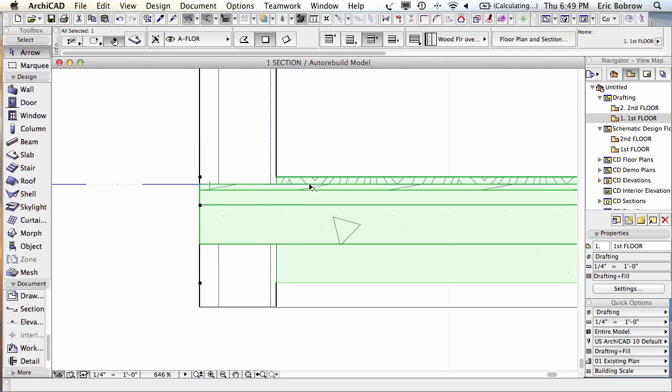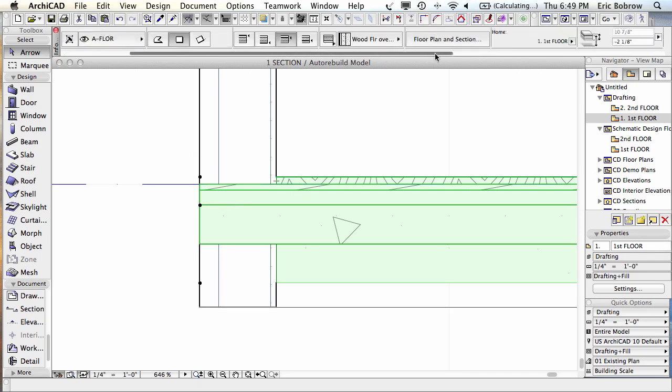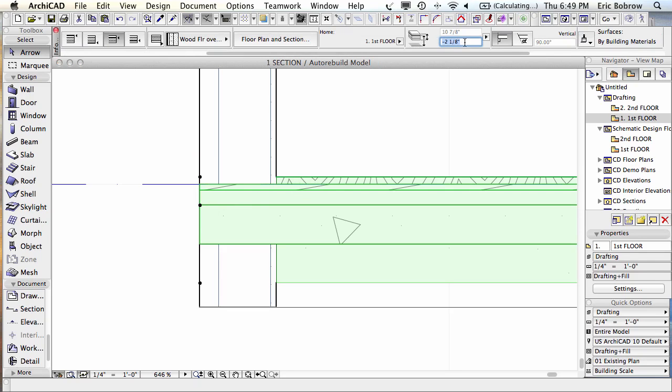So then we have the finished floor on top of that. You can do it whatever way you want, but you'll notice that this now is saying that its top of core is a small distance below the story. So you can do that any way you want. Now we do have an issue in terms of this whole intersection here. The outer skin of this wall is not passing through. Now it's possible we could adjust the priority and force it to go through, but we might want to actually pull the slab back in so that the core goes down. So let's see how that works.